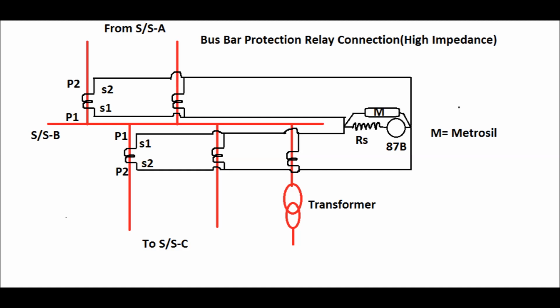A stabilizing resistance is used in series with this relay, and also a metrosil is used in parallel with the resistance and relay combination as shown in this diagram.